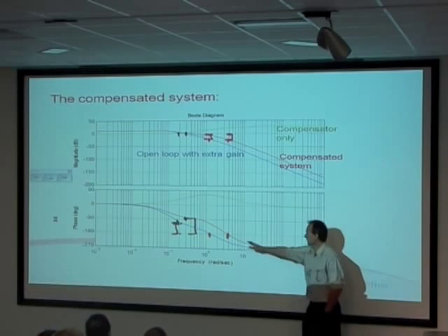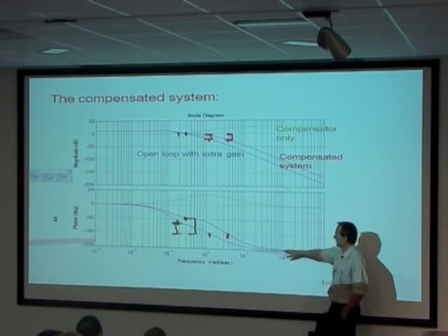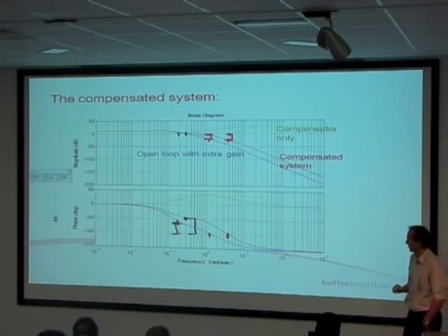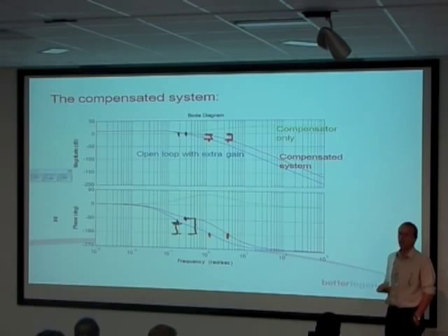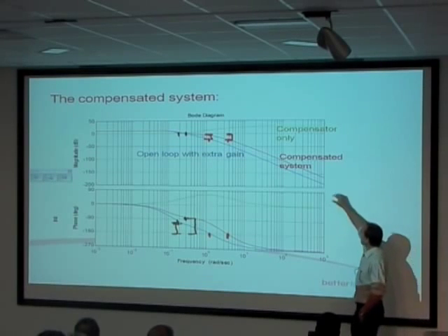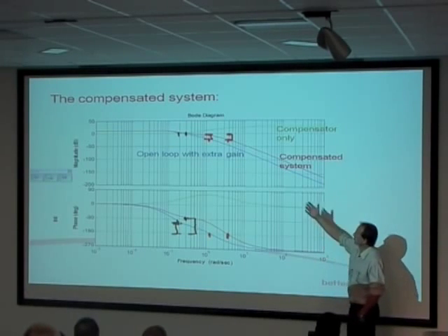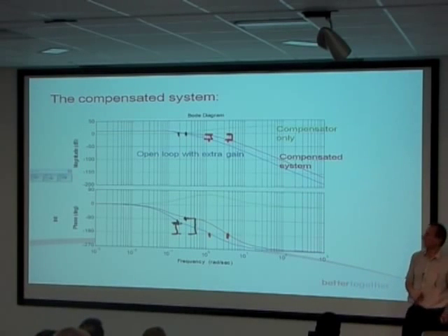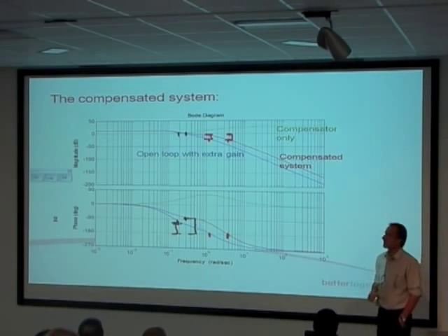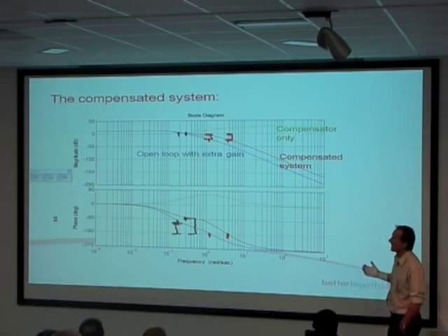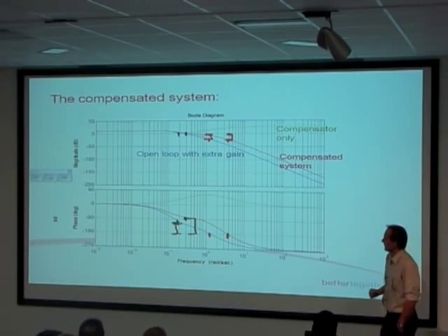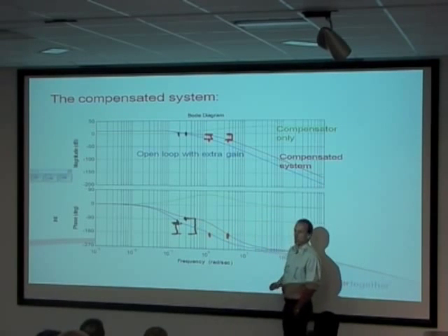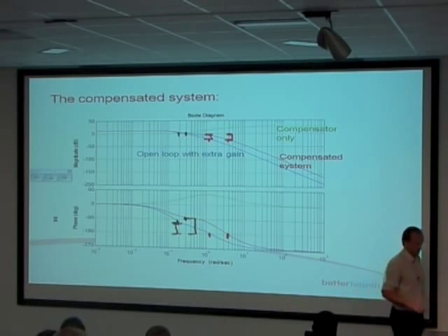Then after a while, of course, when the effect of the lead goes away and my two curves are matching again, I've got the blue and the red coincident in there. I'm stuck with this extra gain, but we're already on that part of the slope where things are all diving down here. We're all on negative gradients. So to some extent, that becomes less important. But we've managed to give ourselves this big lump of phase lead just where we need it.